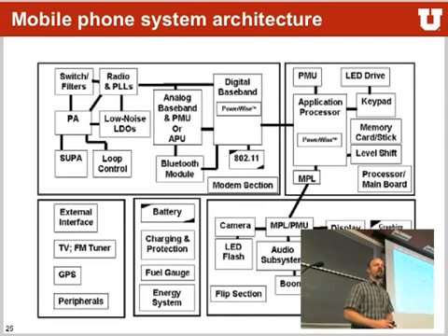And cell phones are really getting complicated if you look at it. What's actually going on in there is kind of crazy. You have power conditioning switches, many different power rails that have to be adjusted and made sure that they come up in the right order after a power up. You have radio chips, the digital baseband, LEDs, external stuff like GPS, Bluetooth devices, and the battery itself that has to make sure it doesn't run out of energy, not too low, or else you will never be able to use it again. They are getting really complicated.